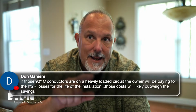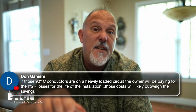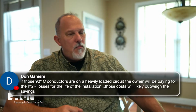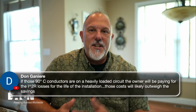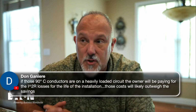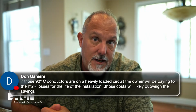I think that 10 amp circuit is targeting those types of branch circuits. And just think, if I had a 10 amp twin downstairs where I can take one spot with two breakers at 10 amps, cat's meow. But here's the problem, Dawn. I don't have a GFCI and I don't have an AFCI. If that goes in the code and if there's a market, I'm sure breaker manufacturers will probably go, maybe we should have a 10 amp AFCI and a 10 amp GFCI.